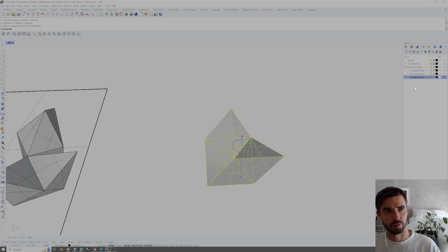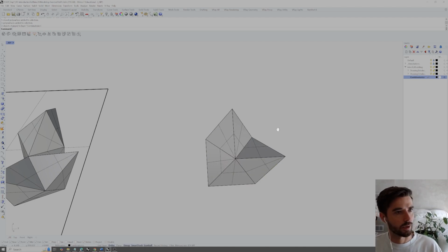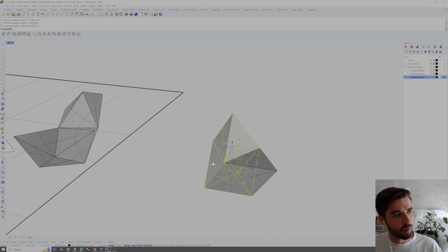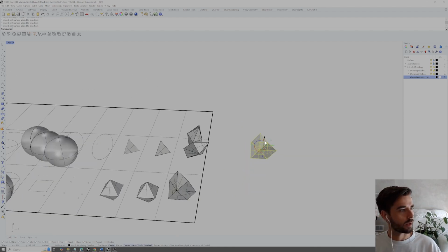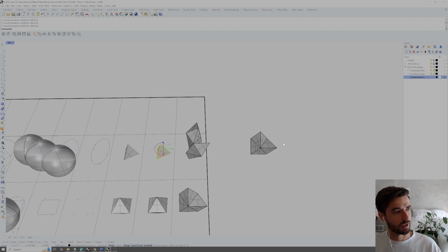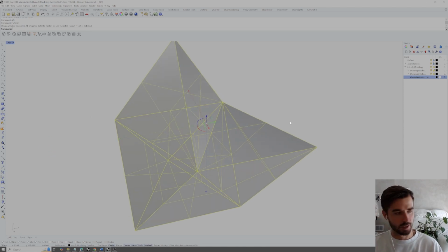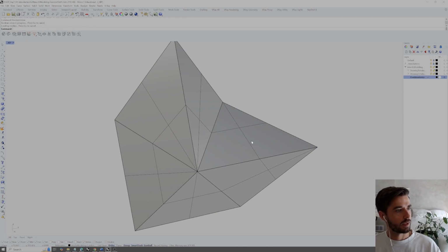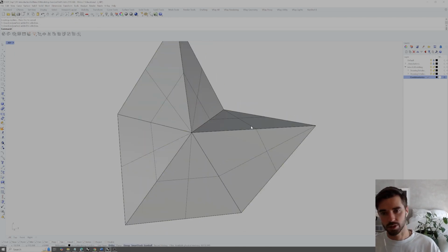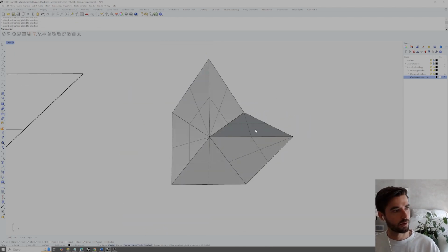I'm just going to double click here, and we'll have the final geometry shown in coordination with the video as I walk through it. So if I know I want these to be my base geometries, and we have our base octahedron and tetrahedron to the left here, then I'm going to combine these from the start. So I'm going to type Boolean union. It will union these as one geometry, so when I click, it selects all of them.